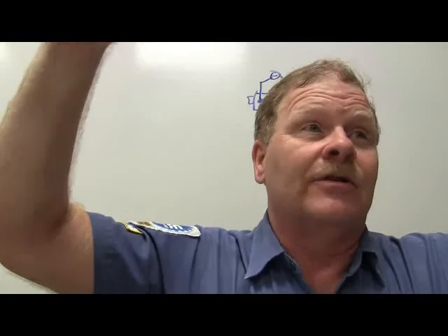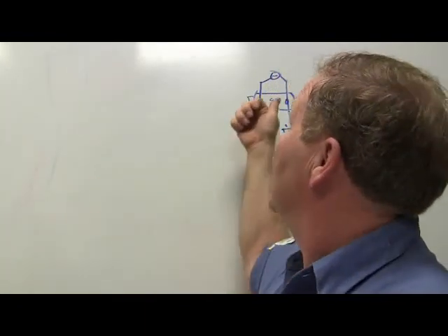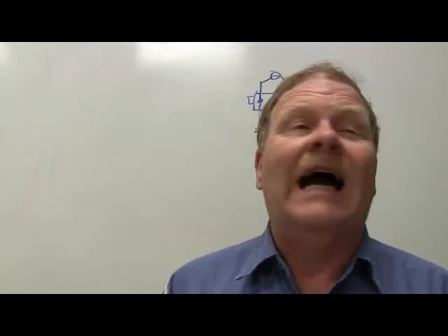All right, I put my circuit breaker in there. Let's say I'm looking at a courtesy light circuit. And you know what's fed from the courtesy light circuit? Your map lights, your mirror lights, all of that stuff. And I notice that when I put that in there and it's clicking off and on, I'm watching all those lights. If it's the lights, it's easier. If it's something else, it may not be.